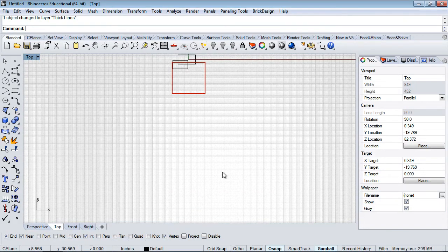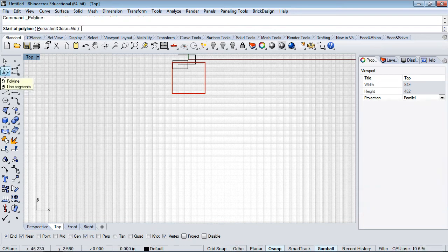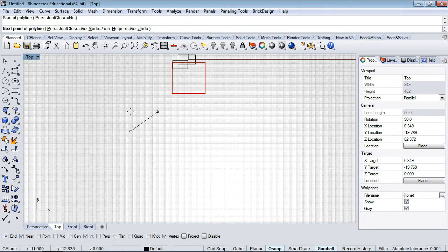Grid snapping means that it will snap to this grid, or whatever grid that you set up. Ortho makes sure that whatever line you are creating is always going to be orthographic, at 90-degree angles, set up to the snaps that you've set up. That becomes really handy. The other way you can do it on the fly is if you're creating a line without the ortho on, you can hold the shift key down and that will lock it on that ortho.